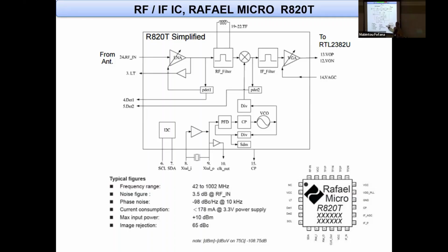You filter, they call it a filter. It's not really a bandpass filter. It's this low pass filter. And then into an 8-bit converter. So it's got an 8-bit sampling device here off of this VCO. So it samples, they call it in-phase and quadrature. It sends out the sampled RF spectrum to your USB port, and on your USB port I set the sampling rate